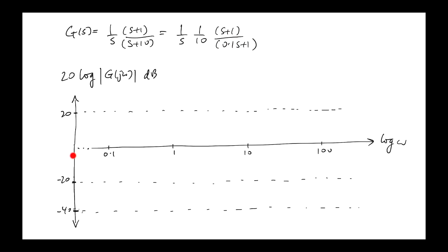Now, of course, you can't ever see 0 frequency on a log scale because the log of 0 is minus infinity, so you never quite see 0 frequency on a Bode plot. But this is on a log scale, so a decade down below this it'll be 0.01, and then a decade below that, 0.001 and so forth, so it gets small quickly. All right. Now we know we can draw the Bode plot by just looking at how each of these simpler functions behave across frequency. Okay, so let's start with this one here.